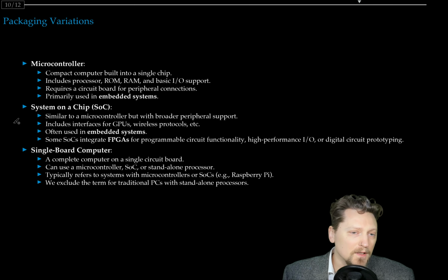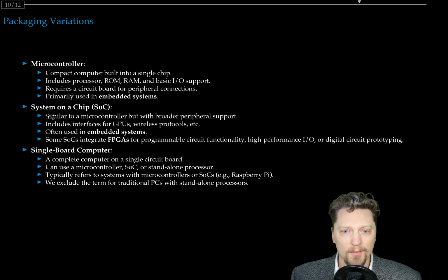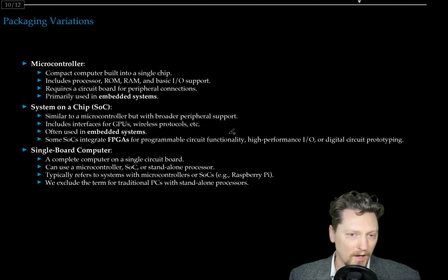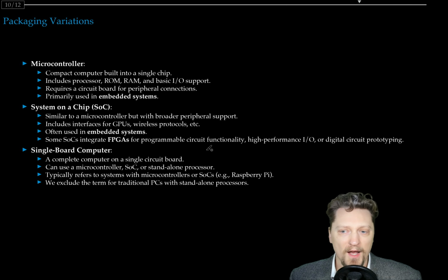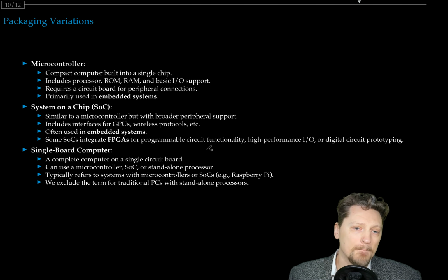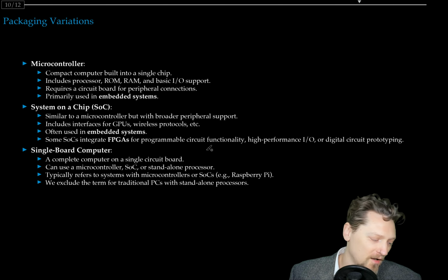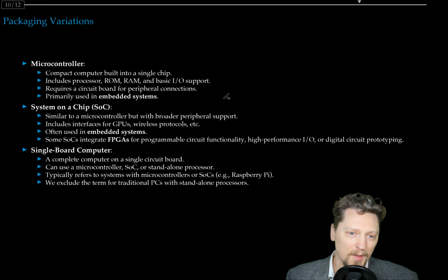There's also a closely related concept of a system on a chip, or SoC. Similar to a microcontroller, but with broader peripheral support. It includes interfaces for graphical processing units, GPUs, wireless protocols, etc., often used in embedded systems as well. Some SoCs integrate FPGAs for programmable circuit functionality, high-performance I/O, or digital circuit prototyping. For instance, the Xilinx FPGA system on a chip that we have includes the FPGA and a microprocessor as well.